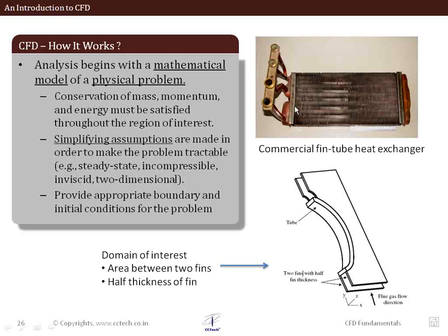Now this is the geometry of a pin-fin heat exchanger, which is typically used for transferring heat in radiators or in household applications in countries where heating is part of a room. You cannot really neglect heating. So we have such fin tube heat exchangers. We have hot water often being poured through these tubes. In some other cases, we have cold water being passed through these tubes, and we have hot air being blown on it. So that's a typical fin tube heat exchanger.